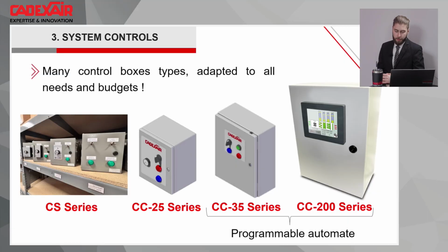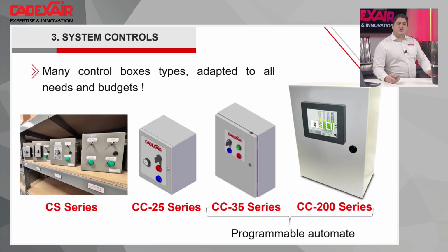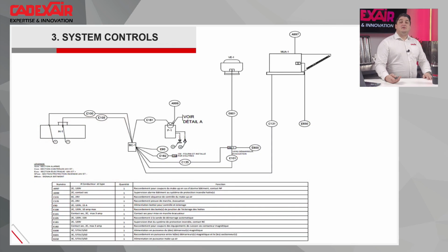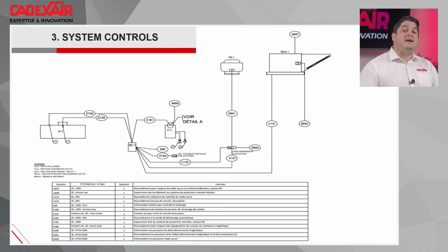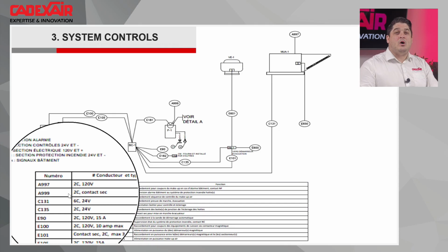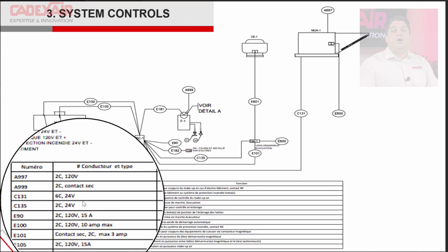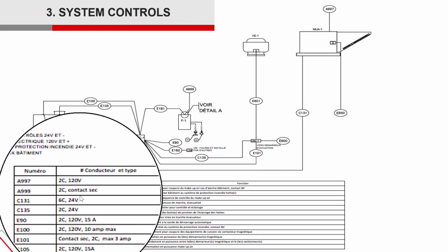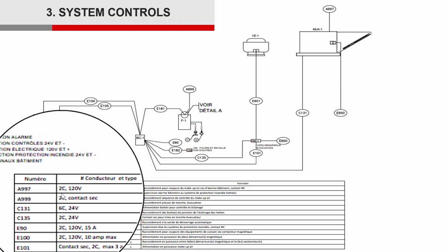Yeah. Perfect. And we also understand the coordination of this is not that easy, so we create a schematic diagram. If you look, every bubble in this is a wire that needs to be installed on site. So there's a lot of information. We try to put each type of wire. I know it's really small, but we put each type of wire, how many conductors, what type of voltage, and also we put a category.